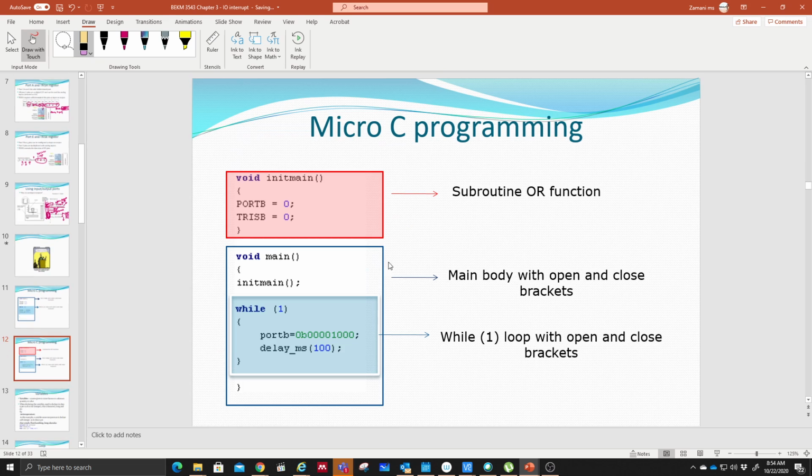Then you have what else? This is another one. You have the body just now. I add this one. We call it subroutine here. Okay, this subroutine, you are actually calling it as an init main. In your void main, this is your main body, like you will go to this one first. We call this guy and do the same thing. You can see that this is actually the setting up process for your pins and your ports level value of voltage. It's the same thing. You can put it over here, or you separate it as a subroutine and you just call this init main.